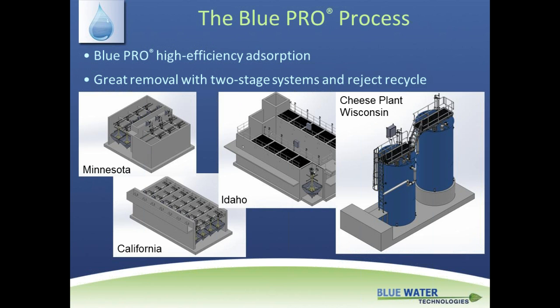And then you're going to another stage that might be lower pH to target elements like arsenic and selenium, some of the nonmetals and metalloids. Also phosphorus, it has a larger adsorption band than a lot of other elements, anywhere from 4 to 10 it will absorb, but it's strongest just below neutral. So those are also applications where you might need a two-stage system.